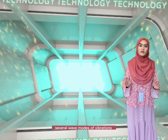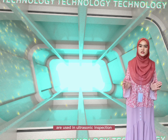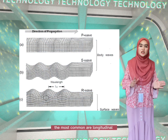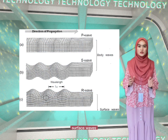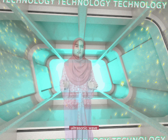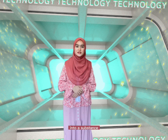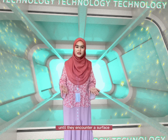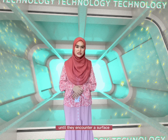Several wave modes of vibrations are used in ultrasonic inspection. The most common are longitudinal, shear, and Rayleigh surface wave. What is the principle of ultrasonic inspection? Ultrasonic waves are delivered into a substance and move in a straight line at a constant speed until they encounter a surface.